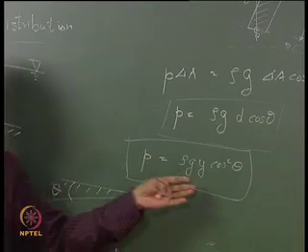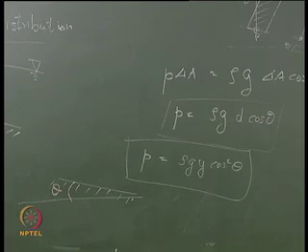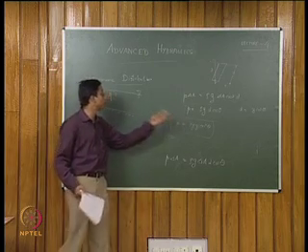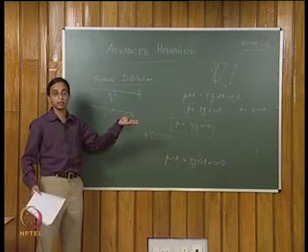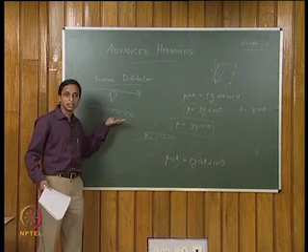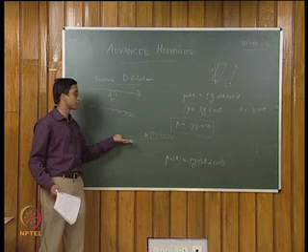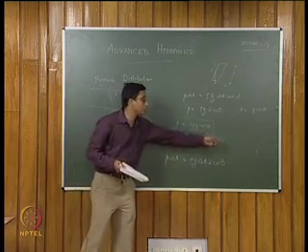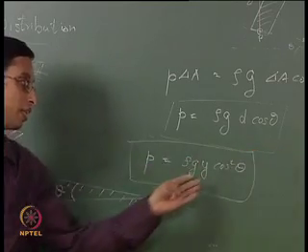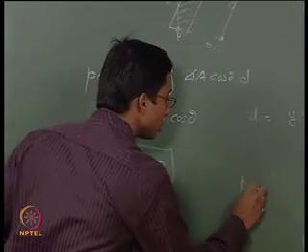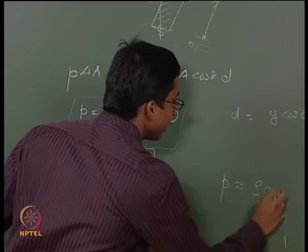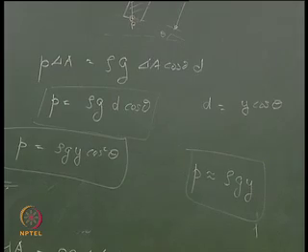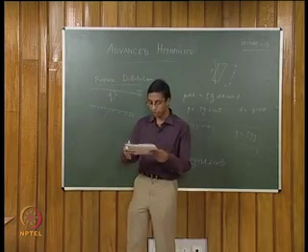So, this is the general relationship you use for finding pressure distribution in an inclined channel. Y is the depth of flow to any concerned point. Even one can easily find now, if your channel happens to be a mild slope channel, where the slope is negligible or not significant, you will see that cos squared theta approximates to 1. Then again you will get the hydrostatic pressure distribution in the channel. Fine. This is how you measure the pressure distribution in channels.